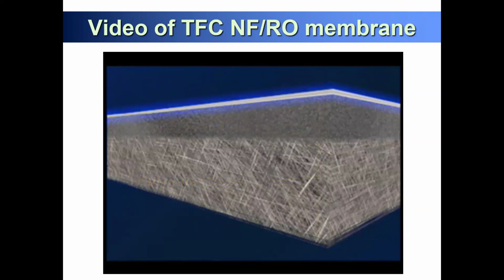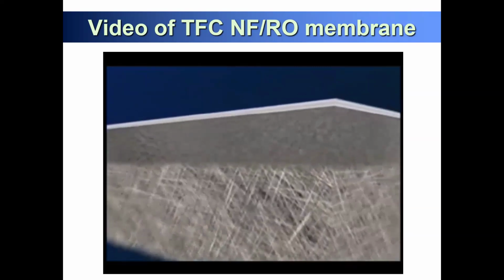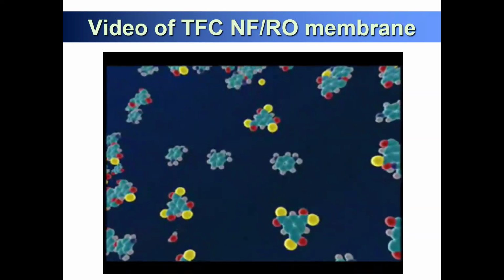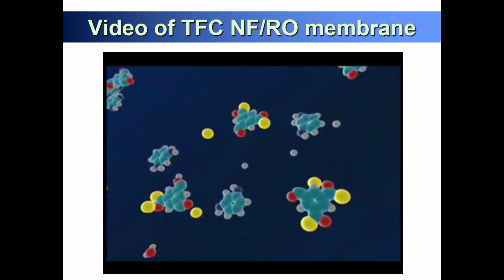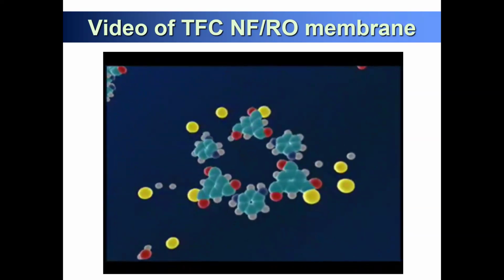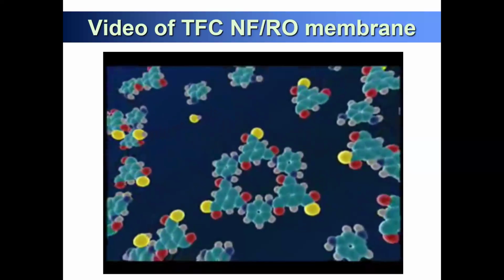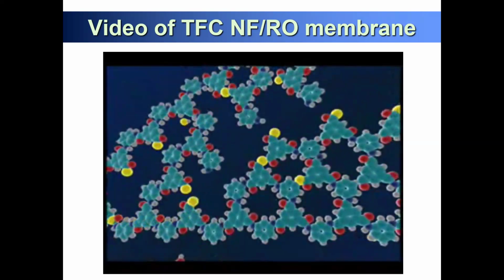The semi-permeable polyamide layer consists of a thin film of polymeric material a few thousand angstroms thick, formed on a porous supporting material. The semi-permeable membrane skin is formed on the polysulfone substrate by interfacial polymerization of monomers containing amine and carboxylic acid chloride functional groups.